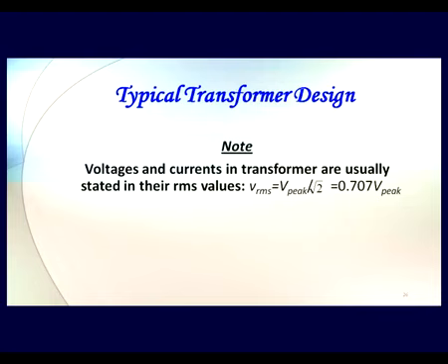Okay, so whenever you are going to choose the components, you should be careful about keeping in mind that the peak voltages and peak currents are going to be higher than the rating you are stating here, and take care of them when you are choosing the particular component for your device.